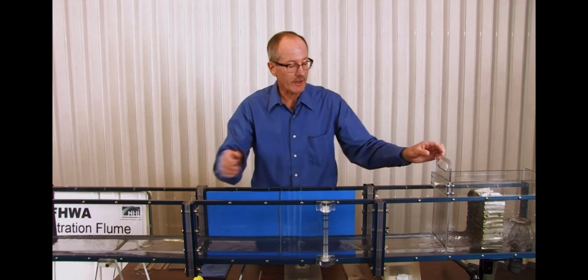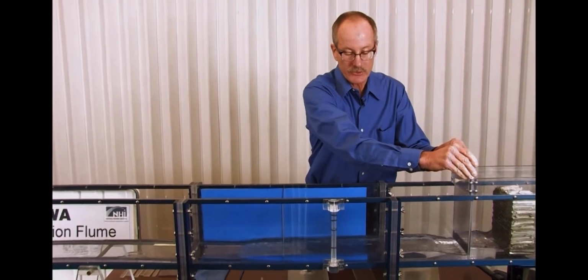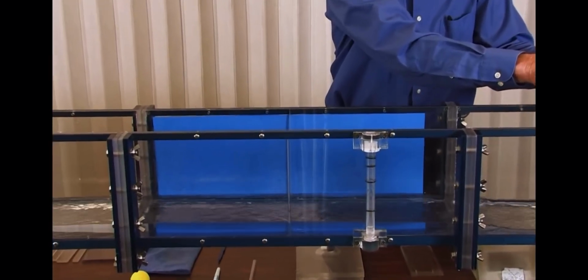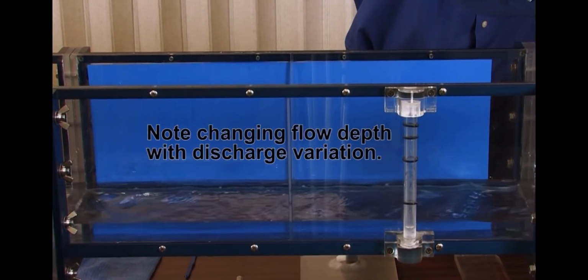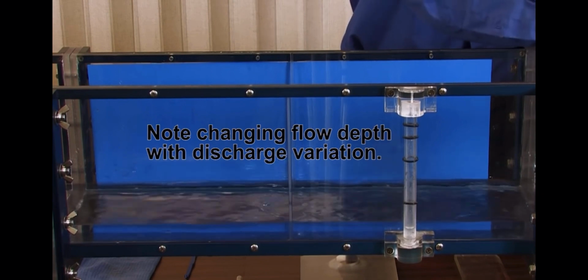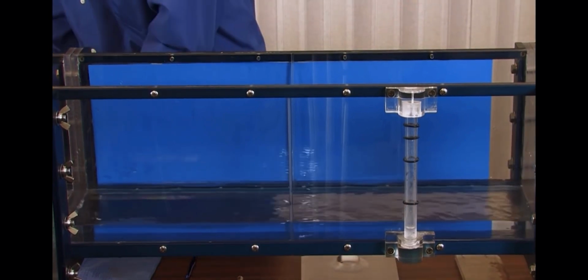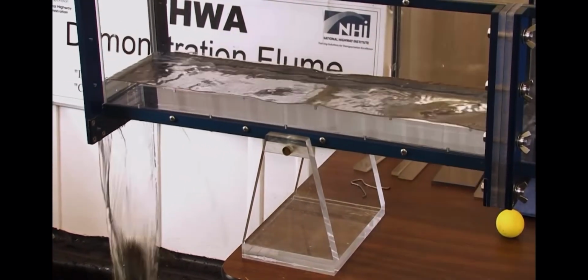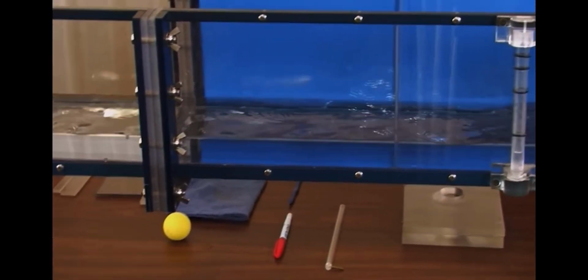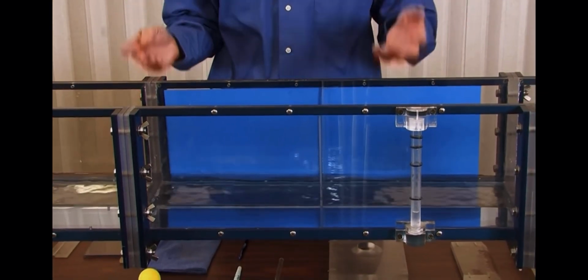If I were to oscillate this sluice gate now a little bit and create changes with respect to time, we have what's called unsteady flow. So getting back to my steady uniform flow condition, if I were to insert some stop logs at the end of the flume, I can create a steady, non-uniform flow.